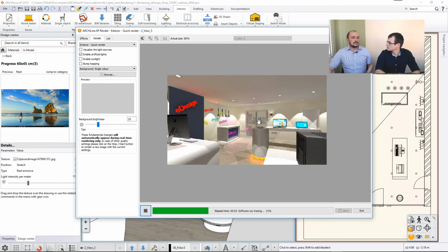So it's just a generic rule that if you have a nice bright scene, go with the lowest setting, you will very likely have a good result. But if you have graininess appearing around these surfaces, then increase the rendering setting, and then you will get a better, smoother result.